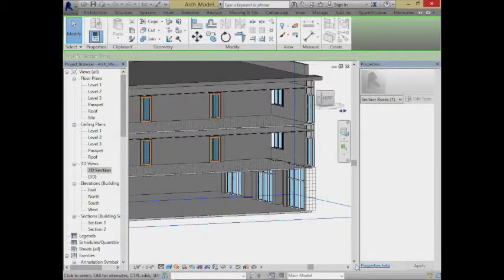Water supply and sprinklers, you could argue about which one's greater there. Sprinklers are all designed, there's back pressure on them. So sprinkler pipes can go up, down, and around, as long as we get the amount of pressure we need in each of the different heads. They tend to be fairly regulated about the locations of where the sprinkler heads have to be and how much pressure is coming at each of the different heads. But piping that has pressure behind it is pretty good.